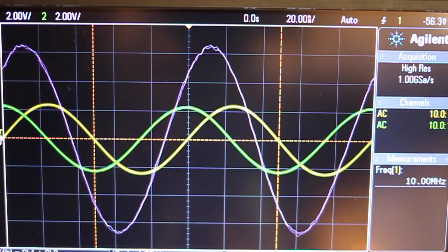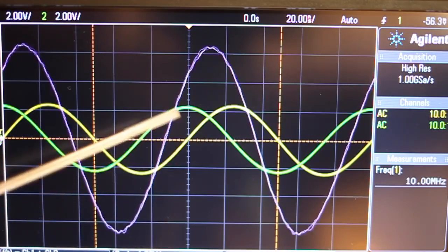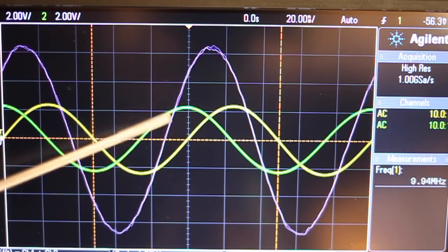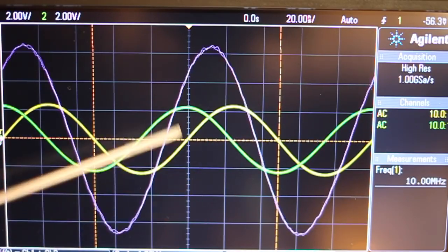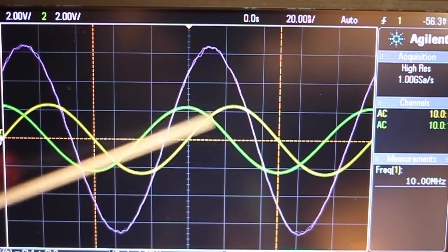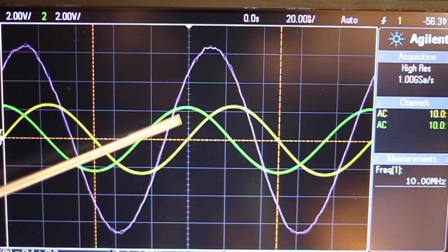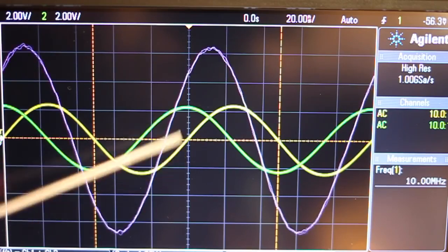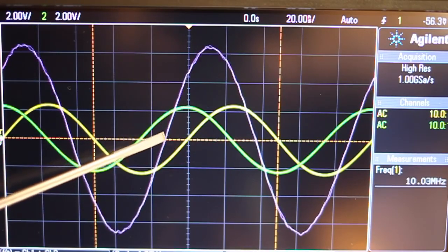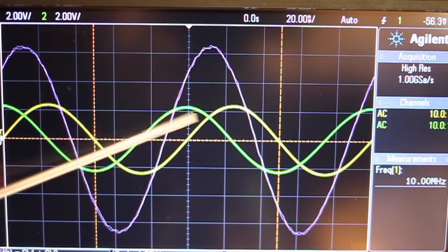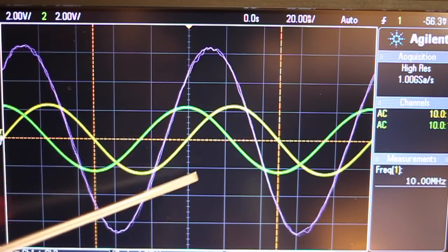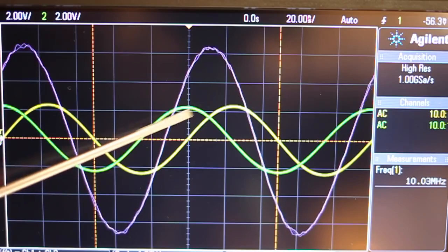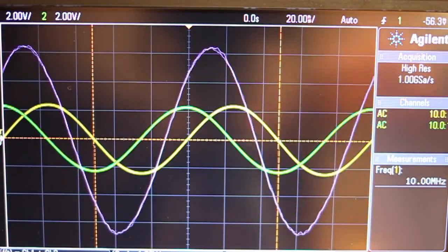And again, the oscilloscope is currently doing exactly that when it's generating this math waveform, which is the sum of these two smaller signals. Now, W2AEW has done some really good videos on quadrature signals, and that's what these are because they're simply 90 degrees out of phase. They're called quadrature, and that's all quadrature is. So I'd highly recommend that you go watch those videos if you want more information about quadrature signals and how they're used to modulate and create these larger waveforms. However, for our purposes, we want to figure out how to deconstruct this larger signal into these two smaller components. For right now, it's just important to realize that you can represent a larger signal by two smaller signals that are 90 degrees out of phase.